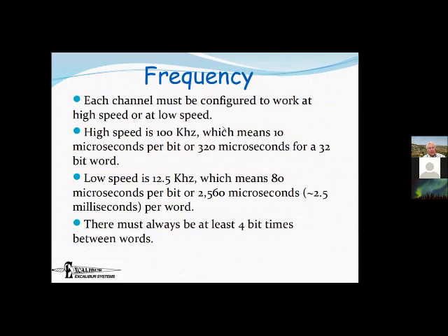Fine, so now we finished discussing what the word looks like, and every word that goes out on ARINC-429 looks exactly like what we've described until now. Every single word has got 32 bits, including a label, including parity. Those are the things that are guaranteed, but within that, you can still show all kinds of different data: latitude, longitude, air pressure, roll, pitch, yaw, roll rate. There's a lot of stuff that you can do, all done in the same 32-bit format.